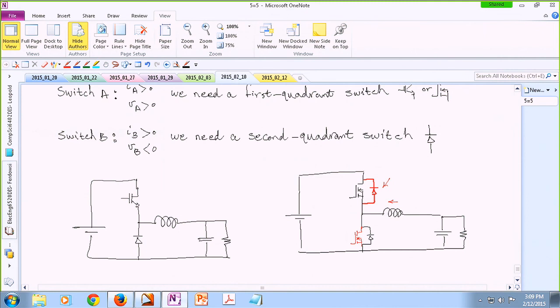However, in the bottom switch, you can argue that if I don't apply anything to the gate of this bottom MOSFET, the body diode of this MOSFET is actually the diode of my converter. Although I can also command this transistor to be on at a good time, and instead of directing the inductor current through the diode, I can direct the current through the MOSFET.